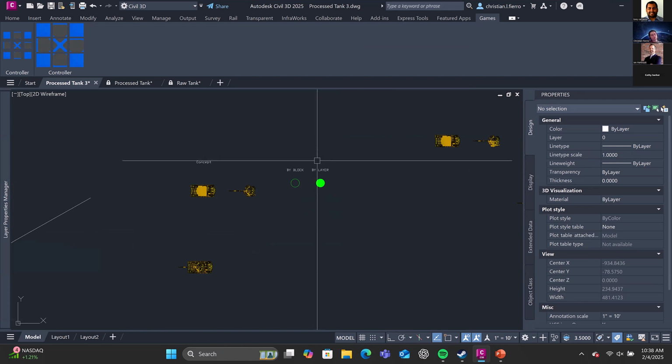And you want to show either this would be an STP or an IFC related drawing or CAD file. And what you would like to do is show this block as red or some other obvious color to where whenever it prints, it shows red.